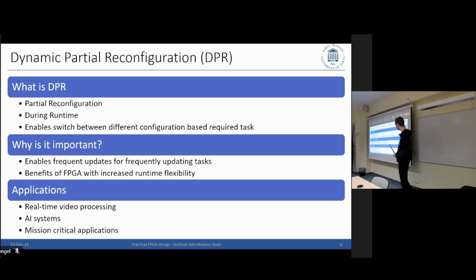And overall, FPGAs get less and less into the high performance domain because there are entities like big tech companies which can afford to make their own silicon. But still the same applies: it is expensive to do your own ASIC or your own tape out of an ASIC. An FPGA will just have a lot of flexibility, or it may even be entirely impossible to have an ASIC because you cannot change your application quickly during runtime. And you're never going to get the flexibility with the performance with any other chip type than FPGAs.